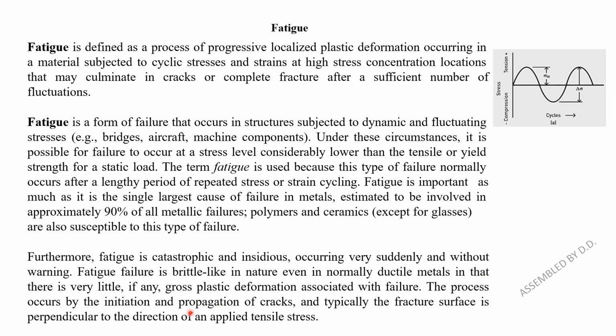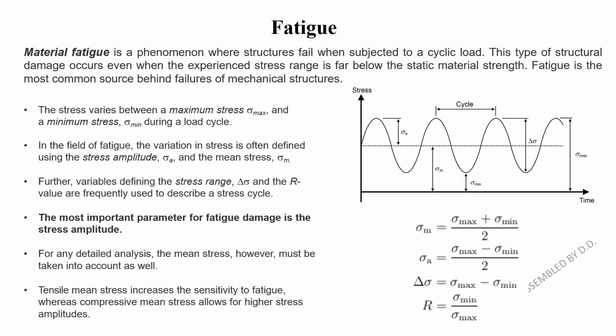The process occurs by the initiation and propagation of cracks, and typically the fracture surface is perpendicular to the direction of an applied tensile stress. Some more information regarding fatigue. Material fatigue is a phenomenon where structures fail when subjected to a cyclic load. This type of structural damage occurs even when the experienced stress range is far below the static material strength. Fatigue is the most common source behind failures of mechanical structures.